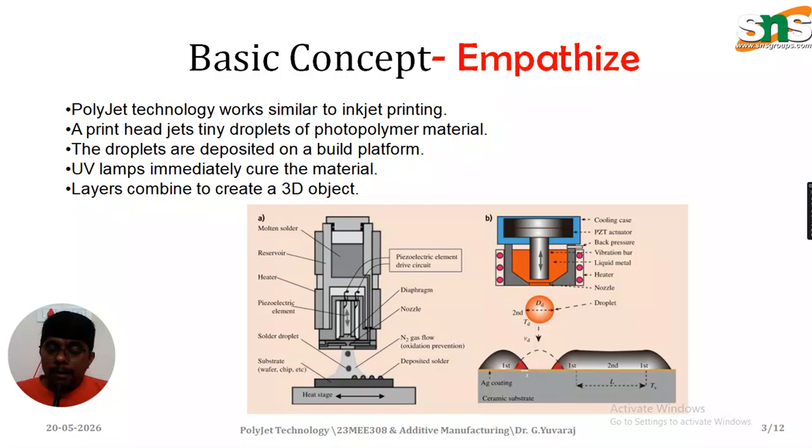The piezoelectric element drives the entire component, along with the diaphragm, the nozzle and nitrogen gases. Solder can be deposited, not only in the reservoir, the heater and the piezoelectric element, but also as solder droplets on the substrate.